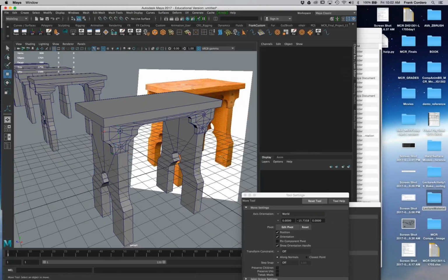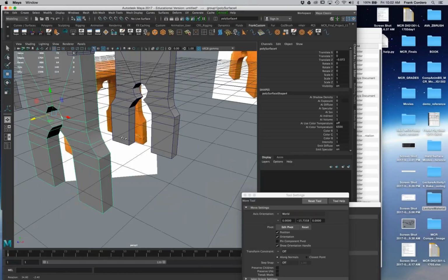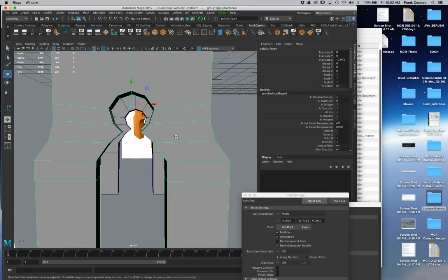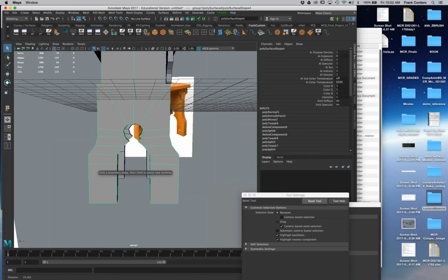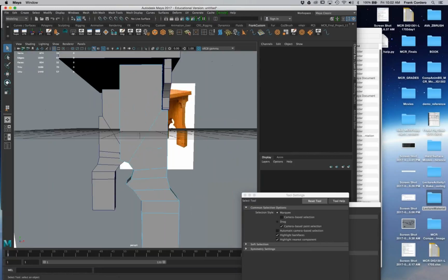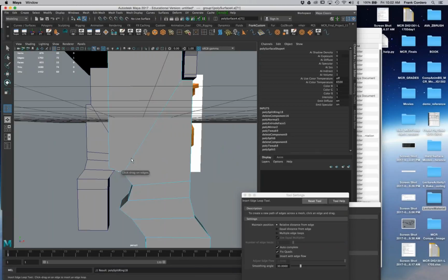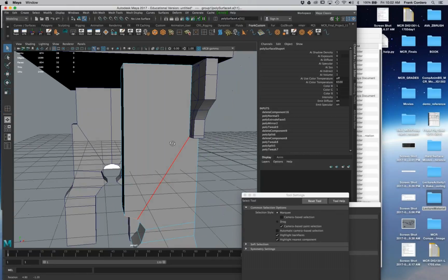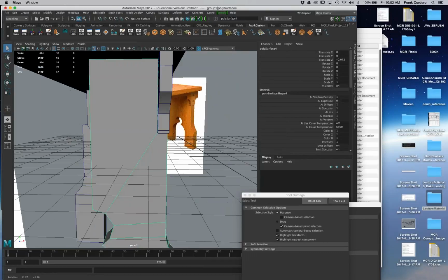Now, I could probably show you manual ways of adding in extra edges. And for a lot of beginners, the issue of adding edges could be something as simple as just doing something like this, where let's say I want to smooth out one side of the model. I might just go ahead and just say, let's go ahead and insert edge loop. Oh, it looks like I've got an n-gon there. Huh, there we go. Yeah, I do. I've got an n-gon. Ain't that a beach?